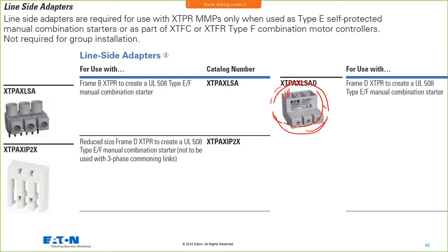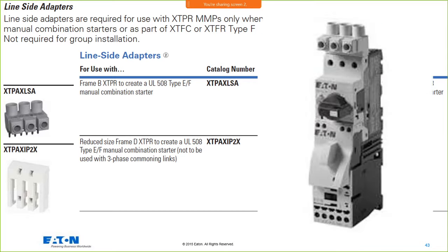When you see these protectors and terminals like this, with these little chutes, you go, wow, why do I have to install that on this application? And why do they have these little tubes sticking up where I'm putting my screwdriver down in there to tighten lugs and whatnot? Well, that's because I need to maintain and prevent tracking of voltage for these higher voltages.